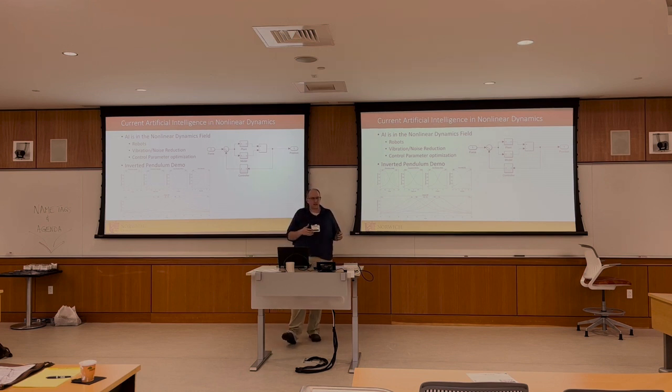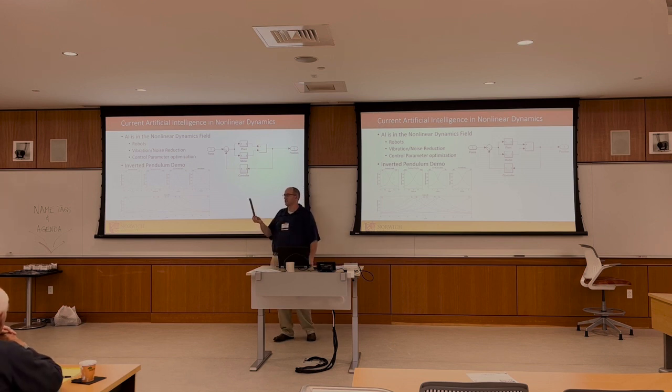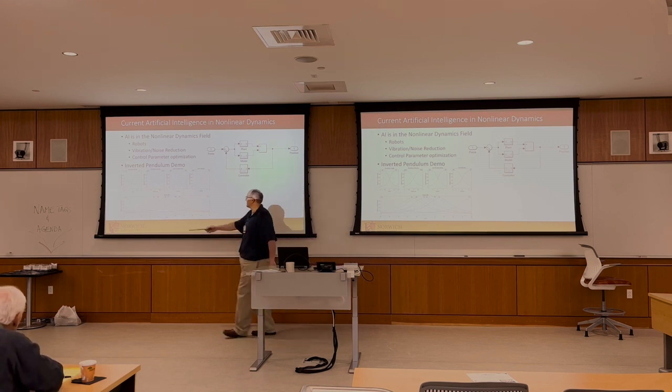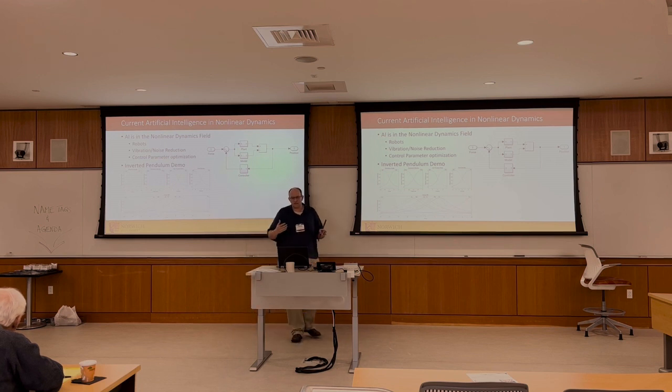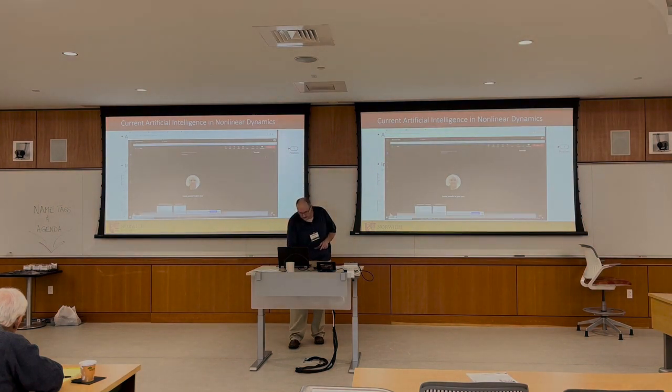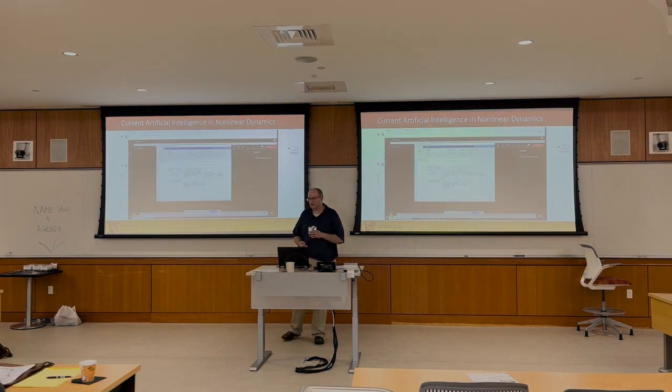So there are different fuzzy logic systems. There's the Mamdani and the Sugeno. The Sugeno is very numeric based. So basically what this controller is right now, where Mamdani is more of a, hey, it's natural language. Like, hey, if this part is moving this way, do this, select this curve right here. If it's at this angle at this speed, select this one. So it's more language based. So with that, I created a little simulation of what I did.